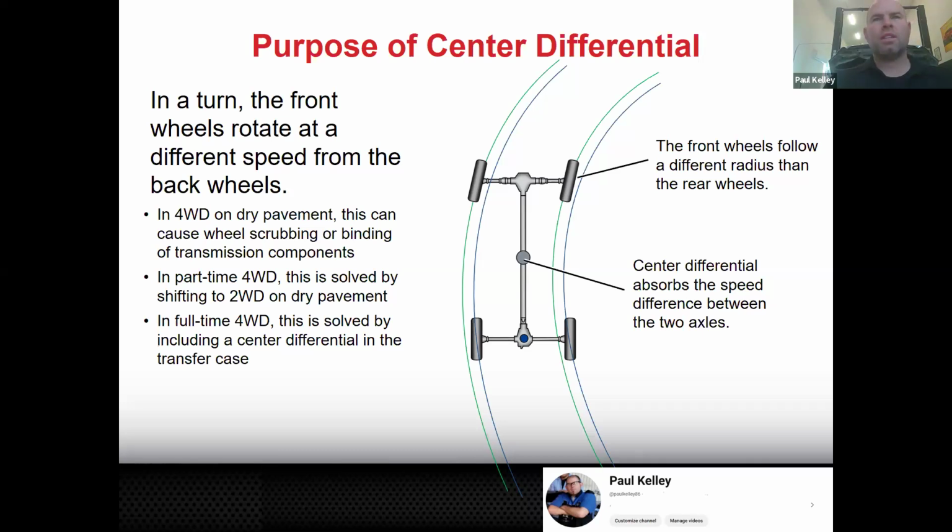The issue with that is it's not a great differential. It's an okay differential, meaning it can handle these turns. It'll let the clutches slip. It's good. However, if you were to have small tires on the front and big tires on the rear, then your rear would be going slow all the time and your front would be going fast all the time. Those viscous couplings don't handle that. That's not what they were made to handle. Anytime there's a big speed difference, it's going to try to auto lock, right? And when it tries to auto lock, it applies the clutches. And when it applies the clutches and you drive 10,000 miles, the clutches are burned out because they have been partially applied the whole time. Makes sense? It's got a little wet clutch pack in there.